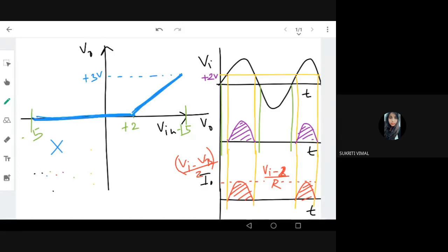So these types of circuits are used to limit the voltage waveforms. We are just trying to reduce some portion of the waveform beyond the limit. Here 2 volt is reduced using the V bias of 2 volt. We are reducing the voltage. Okay. Now what is this? This is V minus 2 volt.